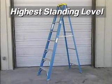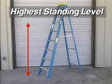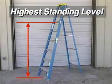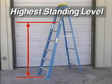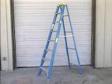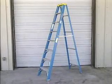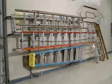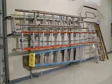Plus, the recommended highest standing level of a stepladder is less than the ladder's total length. The recommended highest standing level is the vertical distance from the uppermost rung or step that the climber should use to the horizontal plane of the ladder base support, with the ladder properly positioned. So, make sure that the ladder you choose is long enough to allow you to safely reach the work area. Another factor to consider when you're choosing a ladder is what kind of ladder is best suited for the job. In other words, should you use a straight ladder, an extension ladder, or a step ladder?